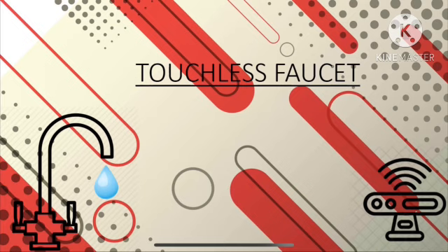Electrical noise, which is commonly generated by other electronic components or external sources, can create errors in the infrared signal. Low pass filtering, adequate shielding and grounding, and differential signaling can all help to reduce noise damage. Temperature fluctuations can also have an impact on sensor function, resulting in drift or inaccuracy. Temperature compensation methods and components with low temperature coefficients can help stabilize the sensor output.